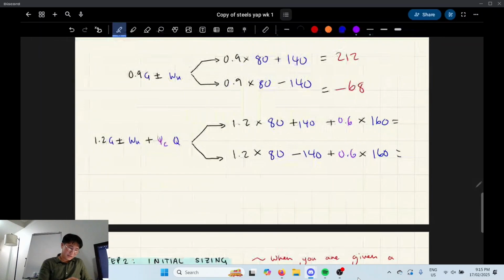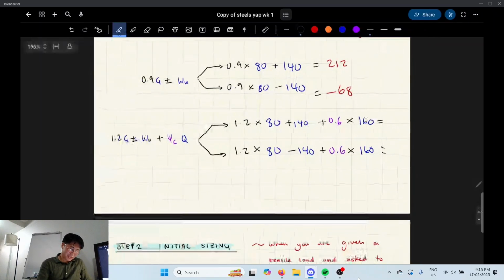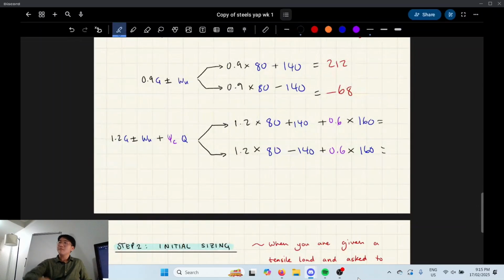I don't know why it doesn't obviously say that. But Prash did this and it's working out. So we're going to put in 0.6. 0.4 for usual. Since it didn't say it in this one, we would assume it would be 0.4. But considering it's a storage building, it's 0.6. If it was a residential building or a hotel, it'd be 0.4. And then these values are going to be this and this.